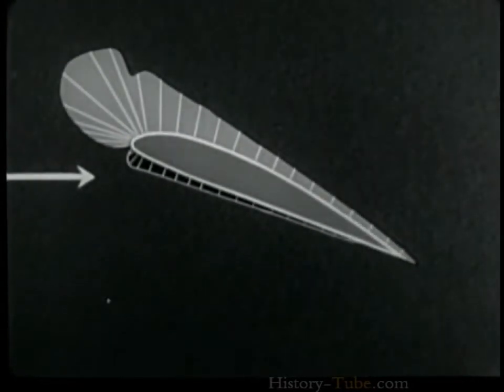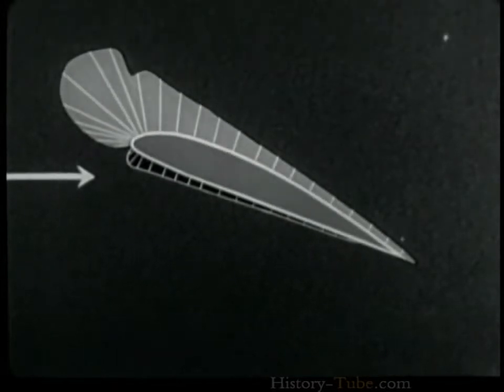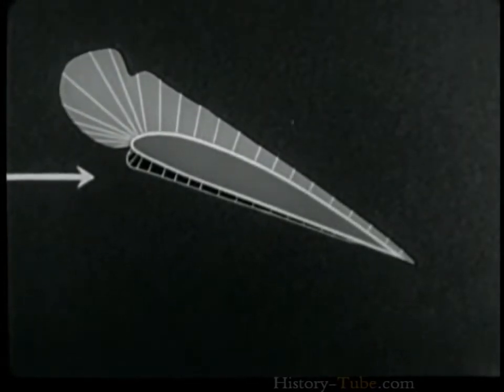At this angle of attack, the wing is well past its stalling angle, yet the positive pressures show little indication of change. With the negative pressures, the greatest change is noticed at the leading edge of the wing, where the area continues to expand, and the outline of the pressure area is extremely irregular.